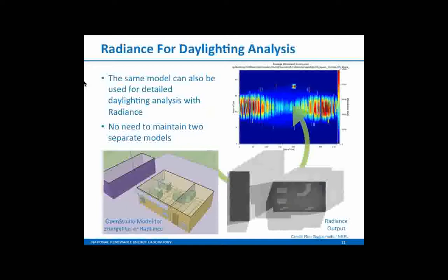So even if it's a big room that may be 50 feet deep with big core space that's not really getting a lot of daylight, and a perimeter zone that's only 10 feet deep because that happens to be how the mechanical system is designed, well, daylight in the EnergyPlus land could never get past that thermal zone, even though there's really no architectural analog to that wall.